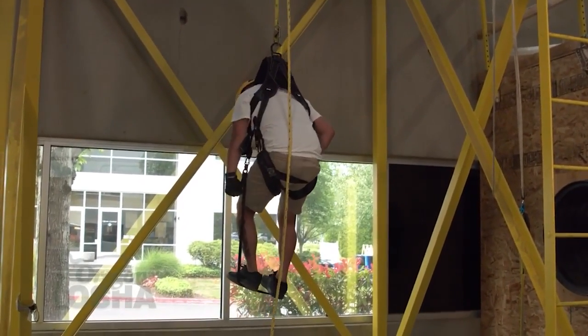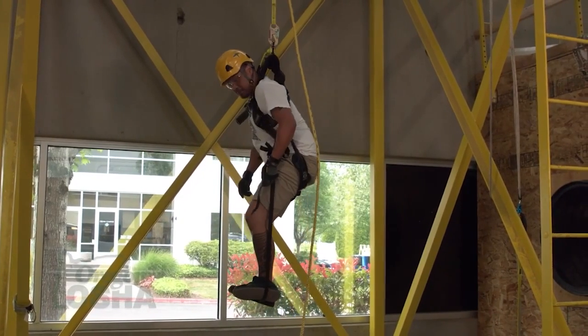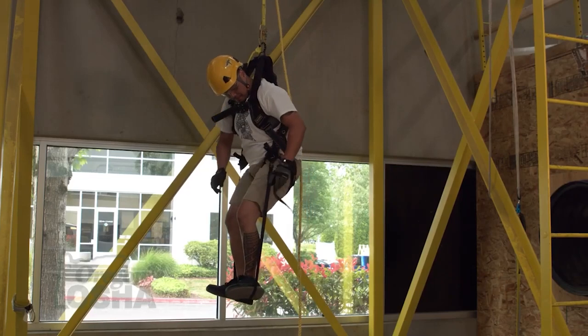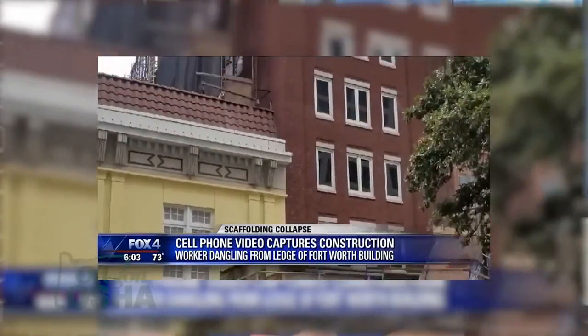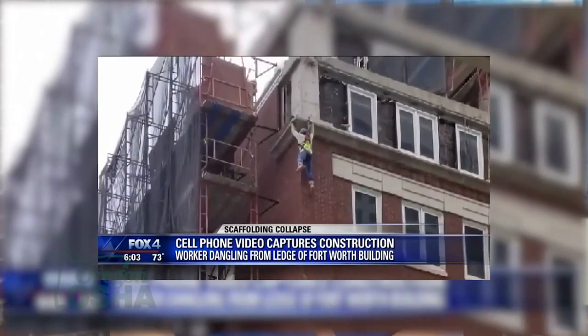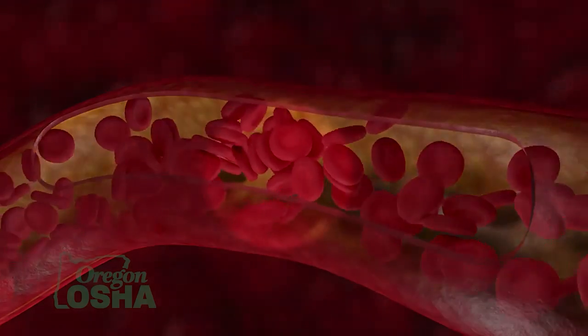If you do fall, you sit in that harness until somebody retrieves you. If you're in an area or somebody doesn't have a plan, doesn't know how to retrieve you, you could be sitting there for a while. If you're 200 feet off the ground, the fire department has to be called, they have to arrive, and you're going to wait there until they figure out how to reach you. You have minutes sitting in a harness while you're dangling there and all the pressure is on the inside of your thighs on that femoral artery until you start to develop a clot.